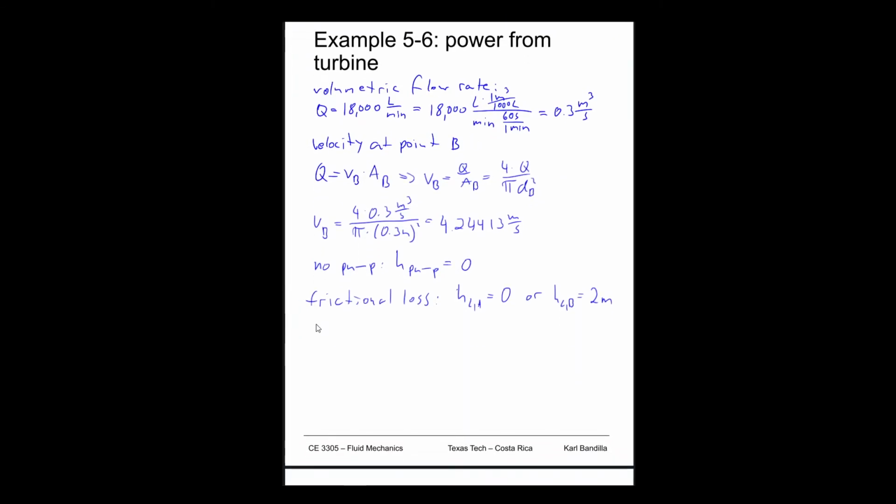All right, so we said that our pressure at C at our inlet is 0. We said that the velocity is 0. We know what the elevation is, and then there's no pump, so that's also 0. Pressure at the outlet at B was going to be 0 as well. We just calculated what VB is, so VB squared over 2G. Then we said we don't have any elevation there, so 0.